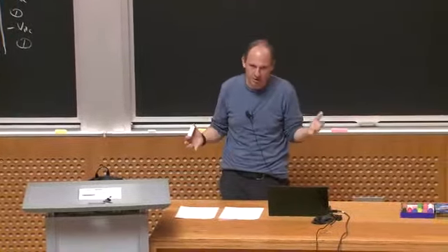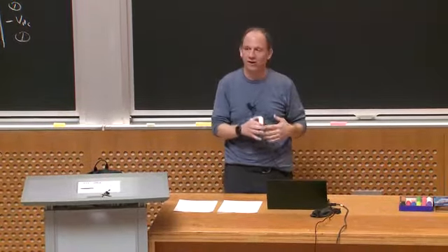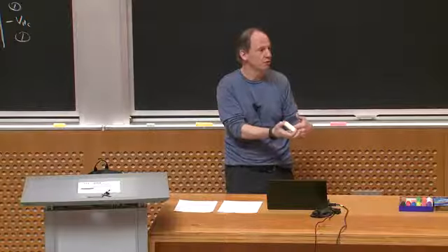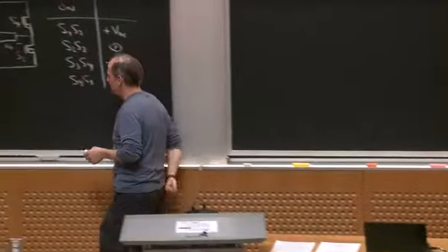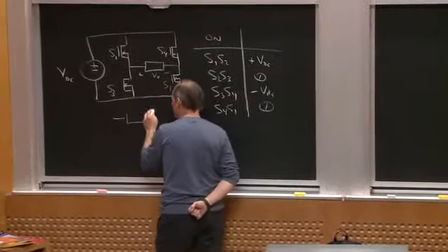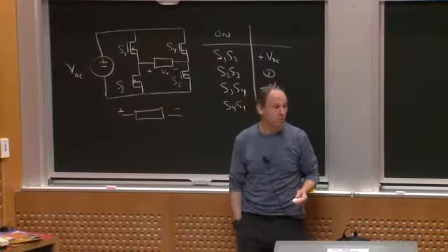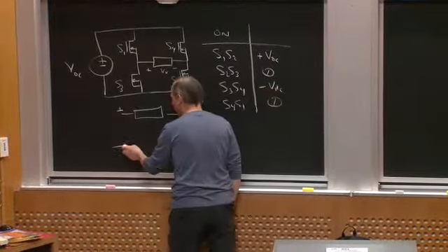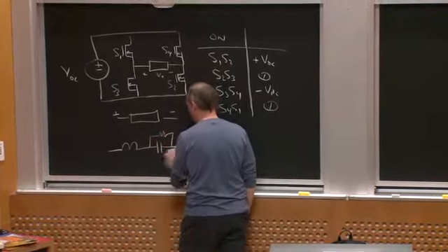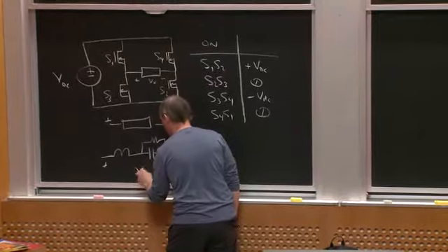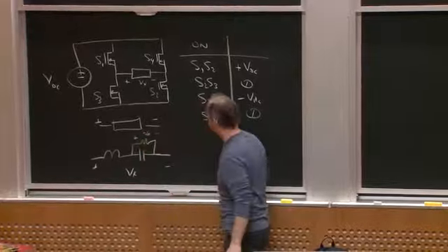And why do I focus on a sine wave? Very often we want to synthesize something that, at least if I filter it, will look like a sine wave. Because, for example, if I'm making a UPS inverter, maybe I would like to replicate what the grid does with my inverter. Okay? And when I show this as a load, what is this? I don't know. It depends on the application, right? It could be a motor winding. It could be some low-pass filter, for example, that's going to some load, right? So this could be Vx, and this could be Vout across the load, okay?